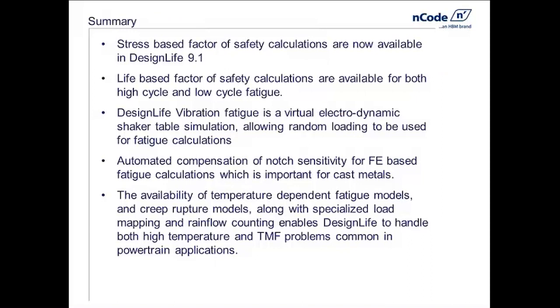So, in summary, what I've tried to do today is describe some capabilities inside of nCode DesignLife that enable you to look at various powertrain applications. We started off looking at a new stress-based factor of safety calculation that's available in 9.1. We also went back and revisited the standard life-based factor of safety that we already had in DesignLife, and that's applicable for both high cycle and low cycle fatigue.